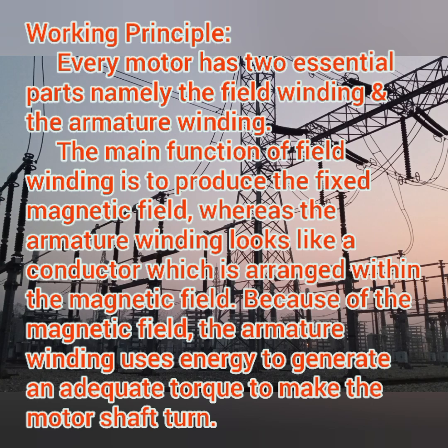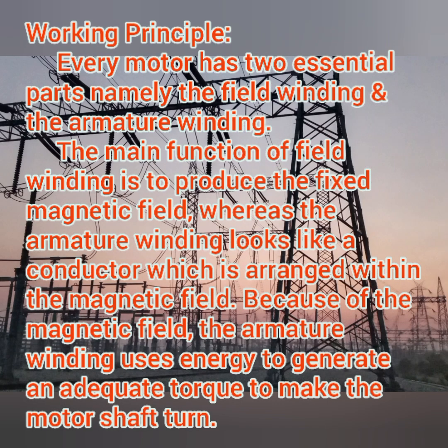Every motor has two essential parts, which are the field winding and the armature winding. The main function of the field winding is to produce the fixed magnetic field, whereas the armature winding is a conductor arranged inside the magnetic field.